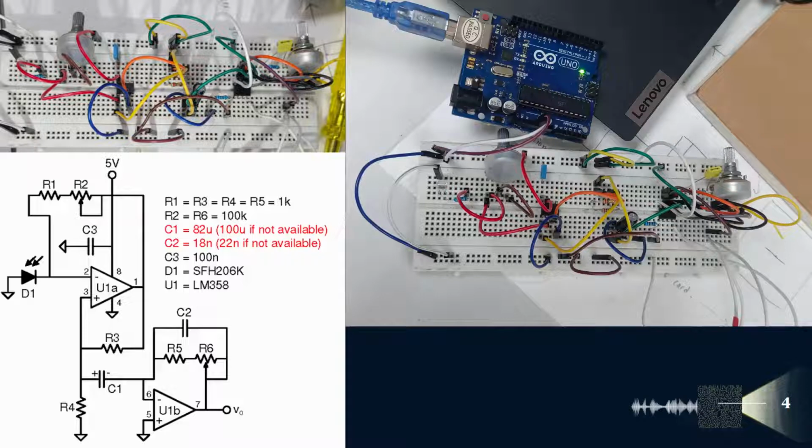Its characteristic is the same as the high-pass filter in the transmitter circuit, namely the one formed by C1 in series with the parallel circuit of R1 and R2. The difference is that the high-pass filter at the transmitter filters a voltage, hence the capacitance and resistance are placed in series.